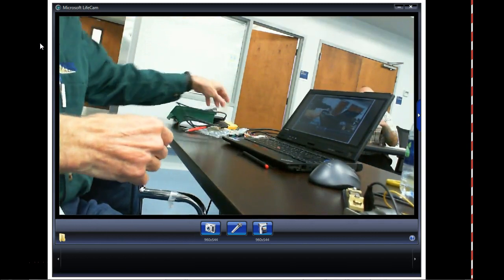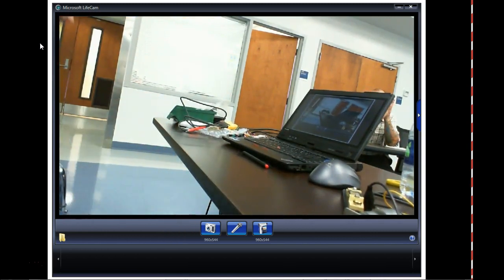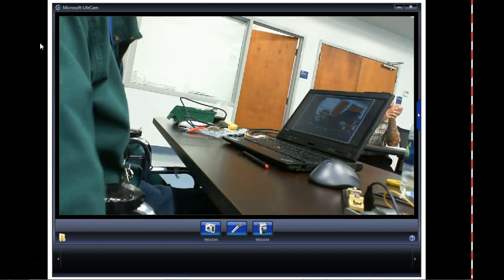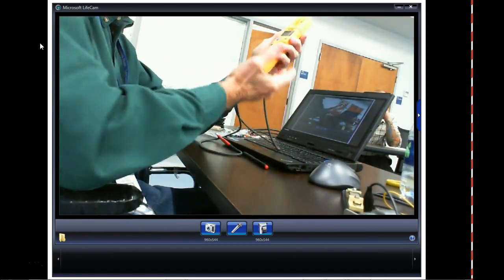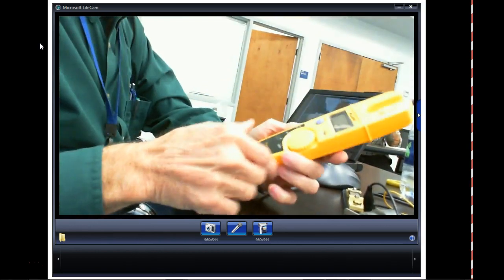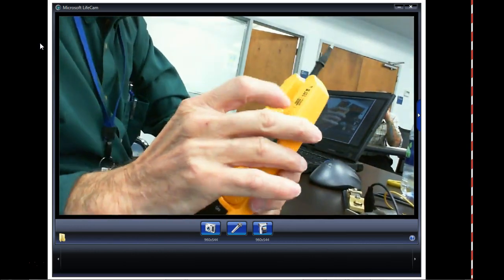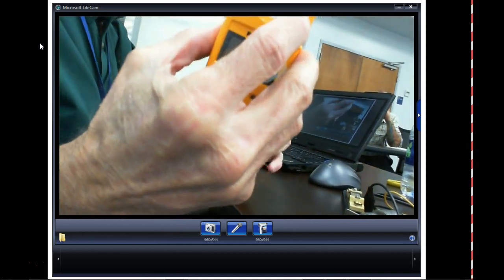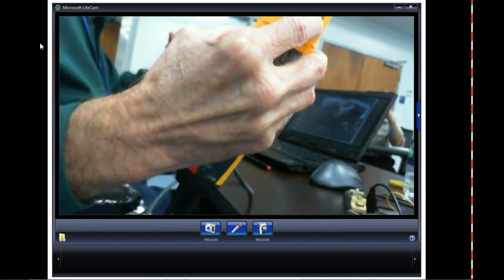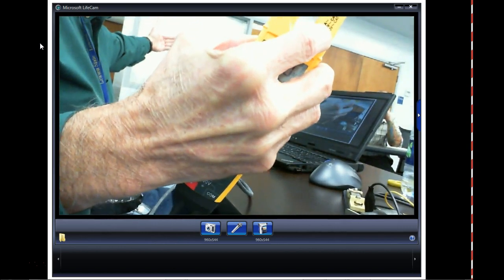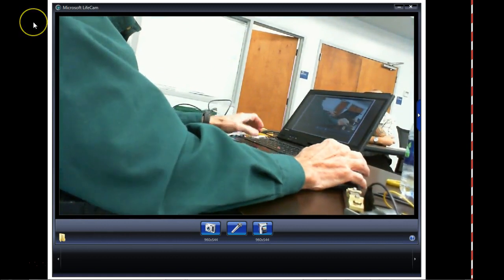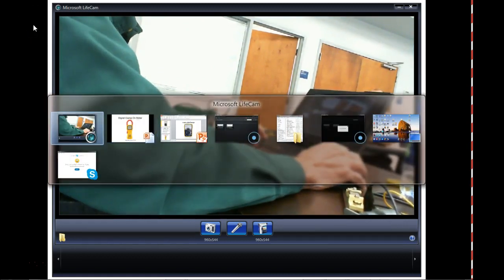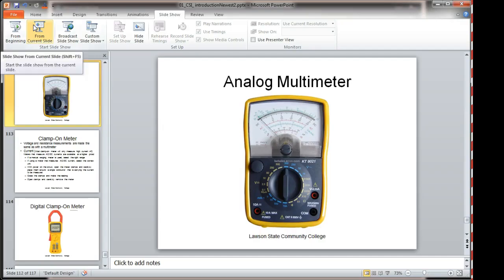So even though the meter might measure 1,000 volts, if I use it on a Cat 4 source, the maximum I should measure is 600 volts. Does that make sense? So it's very, very important to know what you put your meter in.